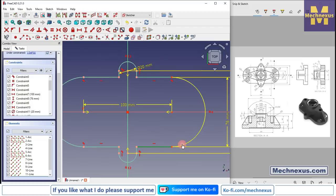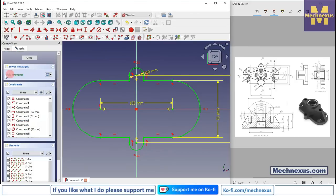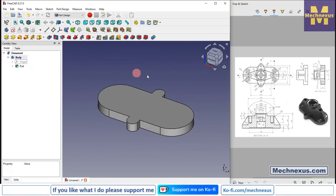And here tangency has gone, so our profile is fully constrained. And here you will get the message of fully constrained, and it is completely green. We will close it. We will select the sketch, click on extrude, and provide the extrusion of 15 mm and say OK.